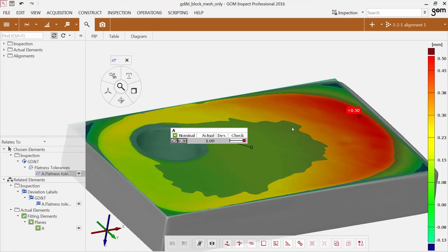In the previous demo, I showed you the flatness check on the datum. If this check is already out of tolerance, as you can see here, it is not reasonable to use it as a datum. In our case, the flatness is far out, so it does not make sense to use it. However, we built the errors on purpose to show you some more obvious errors. In real life, one major player for the function has failed, so the function cannot be fulfilled at this point. However, just to explain what happens next, I will use it anyway.